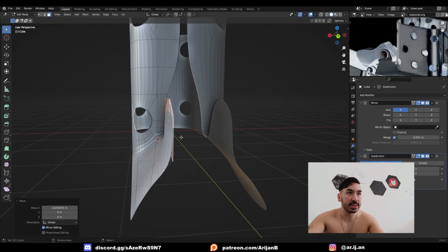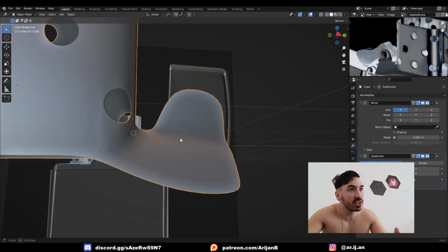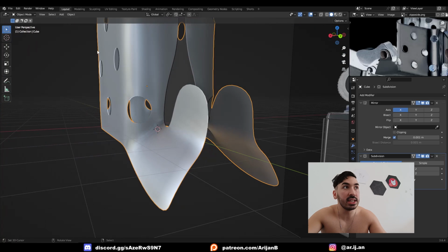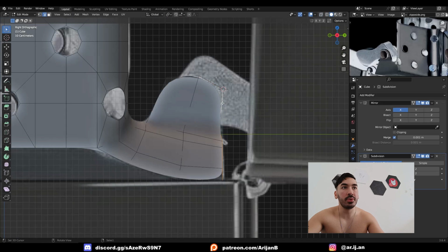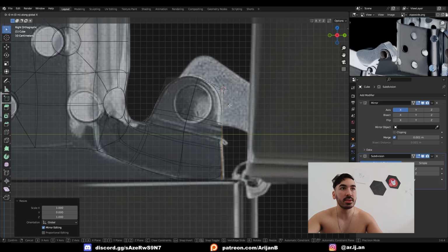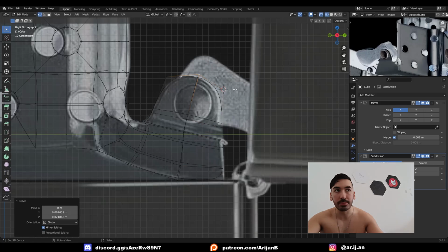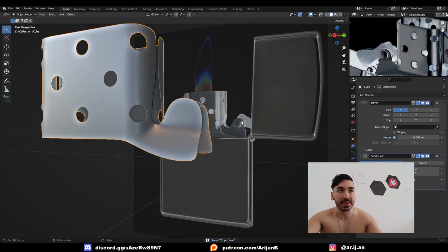So it's gonna be something like this. Notice how none of the face bending makes any difference anymore once we add a subdivision surface modifier. Everything looks nice and clean, especially when you add smooth shading. I'm gonna go over here and make sure that this entire edge loop on the very end is completely straight, so I'll scale it to 0 on the Y-axis and maybe make some final adjustments in case I messed up the shape a little bit. This way we have a perfect shape, and later we're gonna add this little thing here.